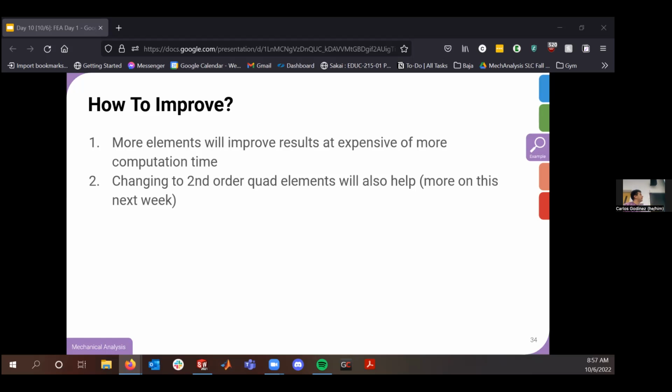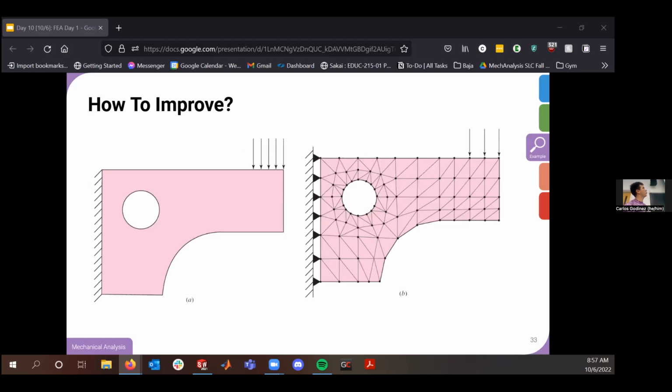The disadvantage is that it's a little difficult to estimate curvature with quad elements, so you're more commonly going to see triangular elements on curves, especially for 3D geometry. But in general, quad elements give a better approximation of what you're going to see in reality, though it's not always the most accurate for weird geometry.